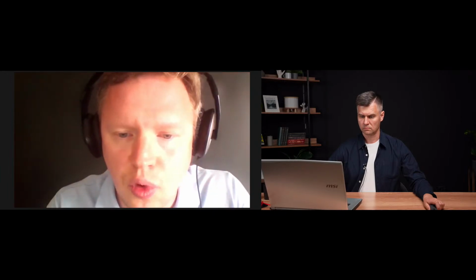Actually, IFC 2x3 and IFC 4 formats are a bit different, and we do not have direct conversion between them. So they are partially compatible, but not fully compatible. So we don't have conversion, and I'd say that it's better to work in the format you are going to save the file.